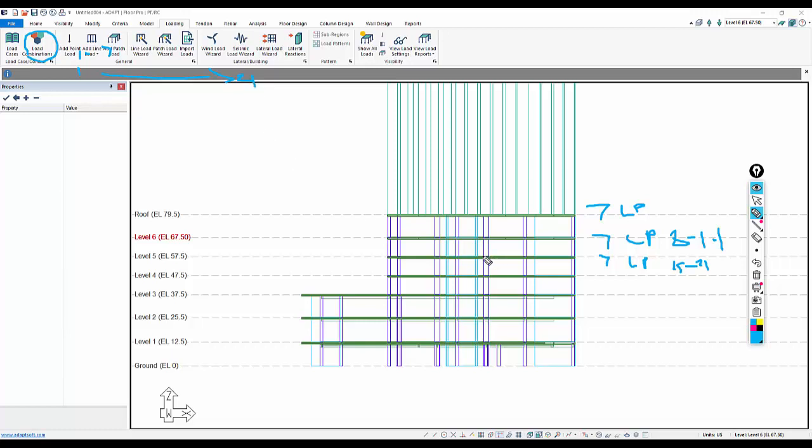If we were running this model globally and we wanted to include the loads for each pattern, we would need to write, maybe we would have one combination, service total, for example. And that service total pattern, we want to determine the stresses based on a global solution, a multi-level solution. We want to determine the stresses for the design strips at each one of these levels based on a multi-level solution. So what would need to happen is we would have to write service total combinations 1 all the way down through 21, and this would repeat for each unique combination.